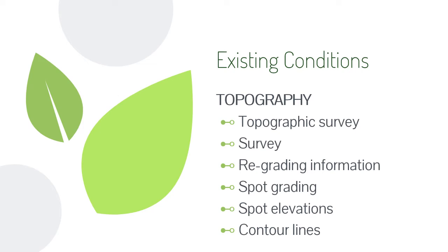One is the topographic survey. It is done by a geodetic engineer, especially if it is an old topographic map. Most of our maps in the Philippines are 50 years or older. Survey is where the cadastral points are. It sometimes happened that the old mohon, as we say in dialect, are gone. So we have to hire a geodetic engineer to look for the cadastral points of the site.